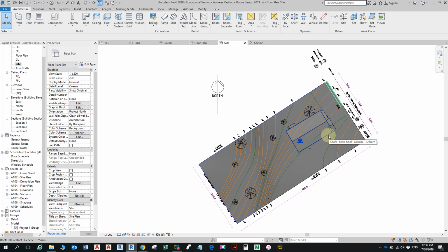You can nudge the house down. Well, the way to nudge the house down in the future or up, it's possible if everything is done on the finished floor level, just change the finished floor level from zero to say 100 or 50 or 46 or whatever to get it right. Yeah, you could do that as well. Yeah. We haven't tried that, but yeah, in theory you can.